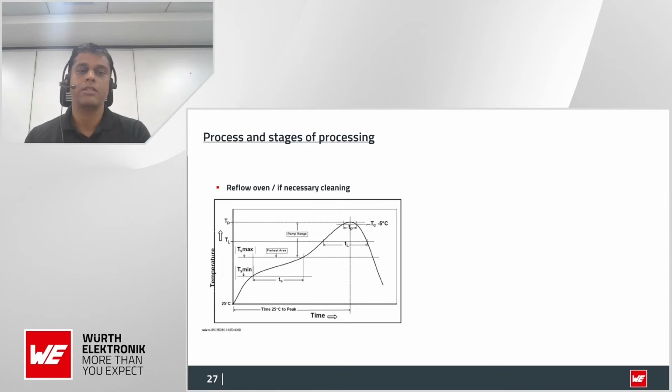The bigger volume product requires higher temperature to get soldered, and the smaller component requires lower temperature to get soldered on the PCBs. So we cannot define each temperature point for each different product. What we talk about is a dwell temperature point. We calculate and bring one temperature point where all the components get sufficient heat so that they can be soldered without affecting component performance. That is called the dwell temperature point.